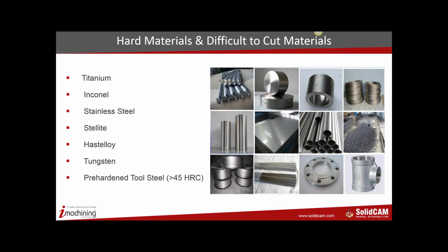The first group is the nickel-based alloys, then iron-based alloys, and the cobalt-based superalloys. The capability of these materials is to perform at near melting point. They go very close. So they're used in applications where they are going to be subjected to very high heat. And this unique ability also makes them extremely difficult to machine. This is one of the reasons why they are so difficult to machine.